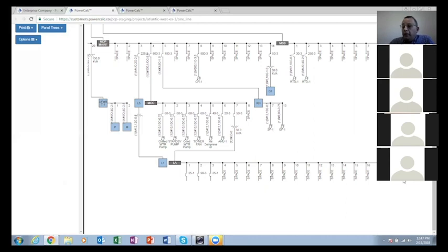Fine, take out the automatic calculation and put in a number 10 conductor or number 4 or whatever you want it to be. Now, once you change the conductor size, it will automatically change the conduit size for you, the ground conductor size for you, all things associated with that one item change.